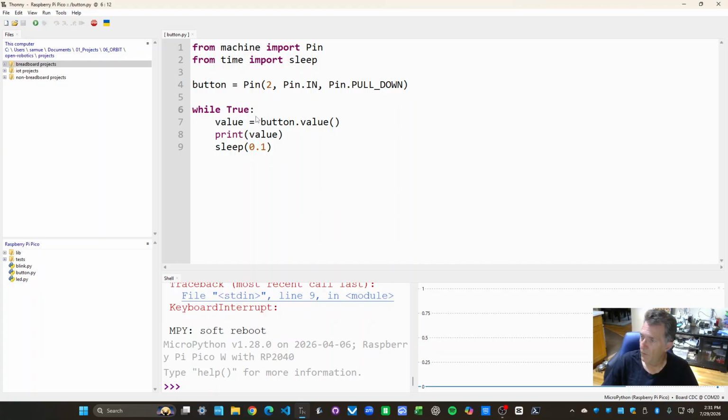Now that we've gotten a button, sure, we can make it go high and low. We can plot it out if it's connected to a computer, but what's the purpose of this? Well, usually when you have a button that's being read by a Pico, it means that we want the Pico to do something when it receives that button press signal.